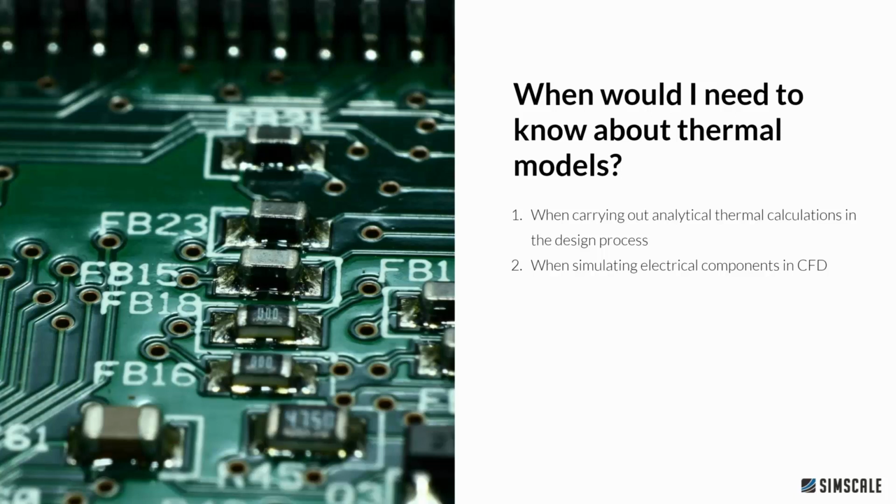So when would I need to know about thermal models? You would need to know about thermal models when you're carrying out some sort of thermal analysis calculation analytically. So for example, if you are designing a PCB and you're in an early design stage, you might do some hand calculations or analytical calculations as part of a program to work out what your temperatures are going to be based upon some ambient temperature.